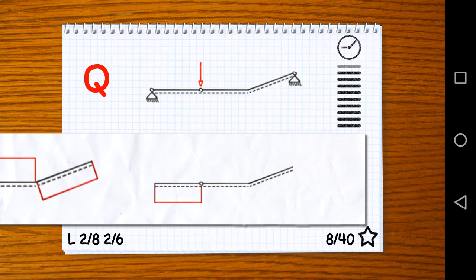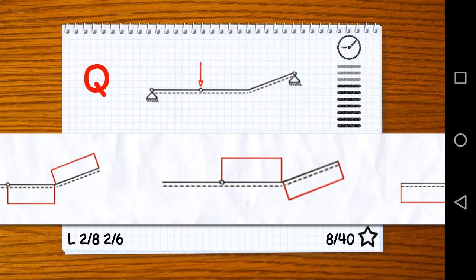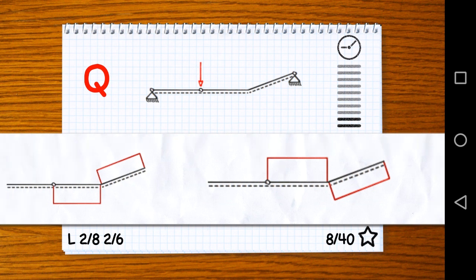Why did we have a jump on the right side? Because of the reaction forces of the supports. But to solve that problem, we only need to know that it's going to be linear going downwards, and that was it. So shear forces again. Look, the left element there from the hinge to the pin support, it's a so-called rod. Why? It's linear. It doesn't have any angle in it. It doesn't have any loading perpendicular to it except at the hinge, and it doesn't have any single moment. So it's a rod. It can't have a shear force.